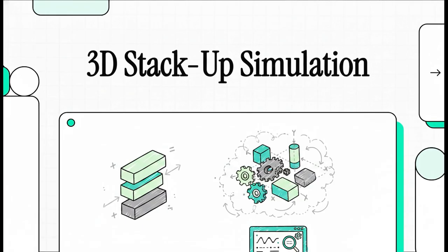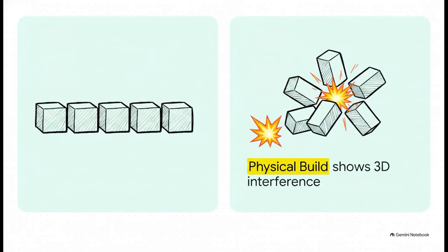This right here is where all that theory you've learned finally meets the complex reality of modern manufacturing. Look, we all know the absolute frustration of doing a manual 1D worst-case chain that promises a perfect fit on paper. You do the math, it checks out, but then you get to the shop floor, put the parts together, and boom, interference. Why does this happen? Well, it's because real-world variation happens in 3 dimensions, not just one. When parts are actually made, they don't just sit perfectly flat. They twist, they tilt, they shift across multiple planes. A single straight line of math literally can't account for what's happening in a real volumetric assembly.